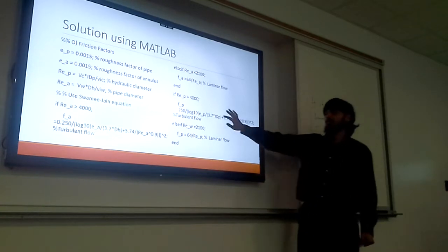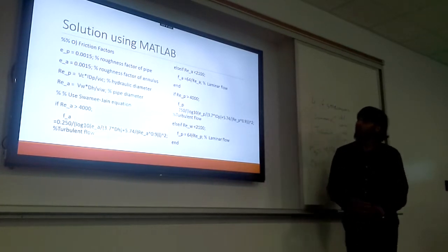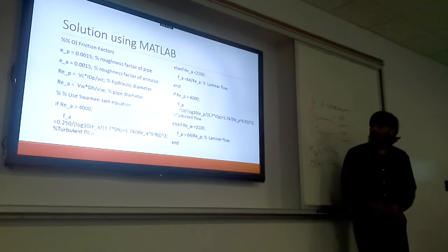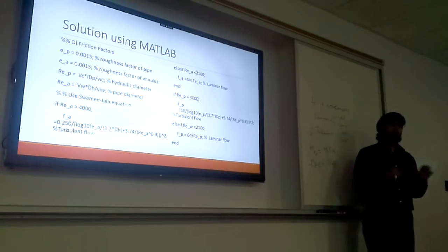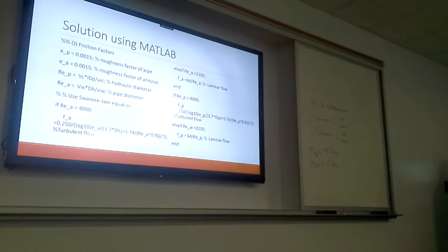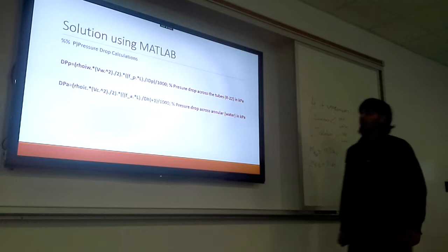And you can get these equations on your own, and you can plug and chug and see for yourself what happens. And after you find the friction factors, and I think for these, they end up being laminar flows, I believe, because they're tubing, the small pipes, for the most part. But nonetheless, from using that information, then you can apply and find out the pressure drop.